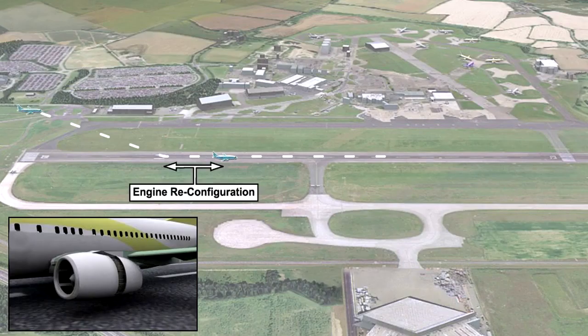However, pilots need to recognize that the process of getting the engines reconfigured to generate full reverse thrust takes time, and so the aeroplane will have travelled a small distance from the touchdown point before reverse thrust takes effect. This fact reduces the effective time period during which reverse thrust can be used. Therefore, the effectiveness of reverse thrust on landing is reduced.